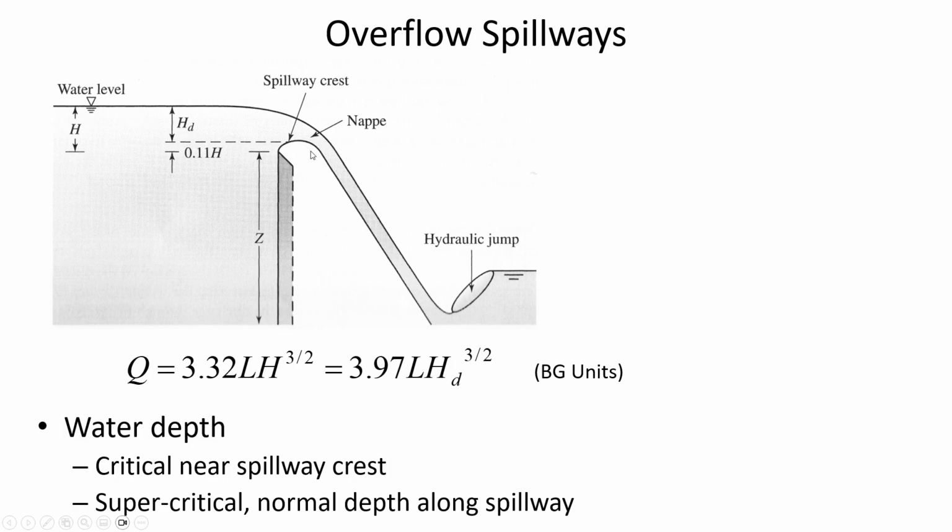It increases the pressure at the spillway crest when the water head is lower, and so that would cause the tailwater, the water upstream of the spillway crest, to be artificially higher than it ordinarily would be. So in this shape of an OG spillway, there's an important reason why we follow that shape.